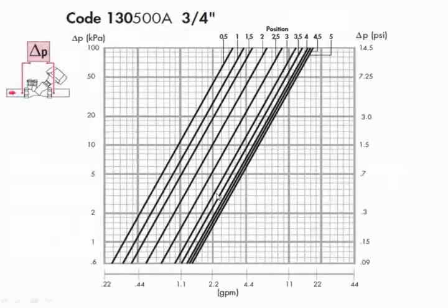So we go back to our chart for the pressure drop across the entire valve now. Now this is a different chart. It's across the entire valve. It's not across the ports because the CV doesn't change across the ports. So we can go to our instructions and we can see for our 3/4 inch valve, the knob position, the delta P, and the flow rate.